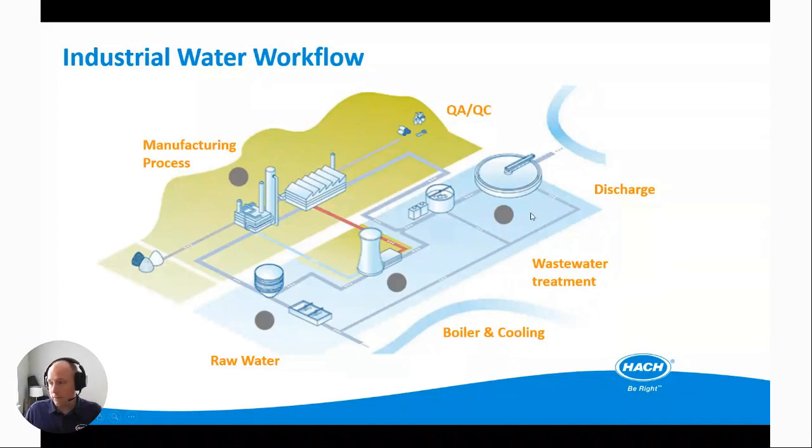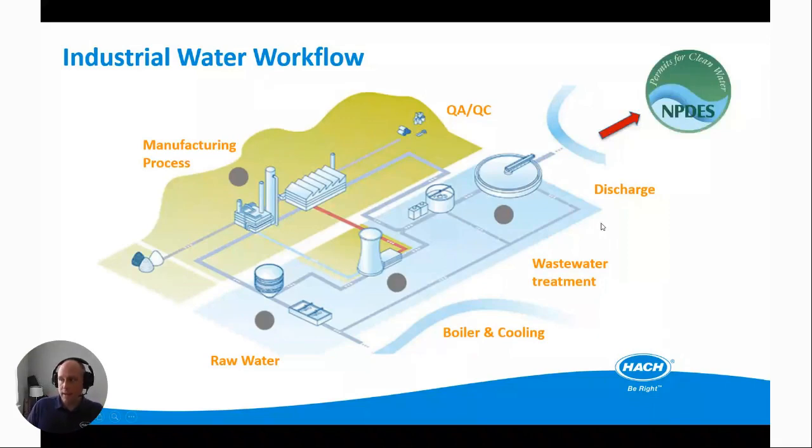And frequently, this discharge is regulated with an NPDES permit. NPDES stands for the National Pollutant Discharge Elimination System. This is part of the Clean Water Act, and that's the program through which the state and the federal governments can regulate point source water discharges.